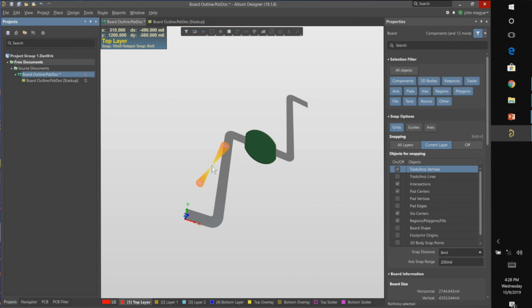Now, if you did this and everything is at rest flat, what if you had some parts that had to be bent up, like for assembly? In other words, you're not going to bend it, you want it molded to be at an angle. So there is something referred to as a folded state, and you can put this into that folded state, and you can save that out as a 3D model in that state and work with a physical verification to do that. But generally, because it has to be manufactured flat, it can be bent and used however it's needed.